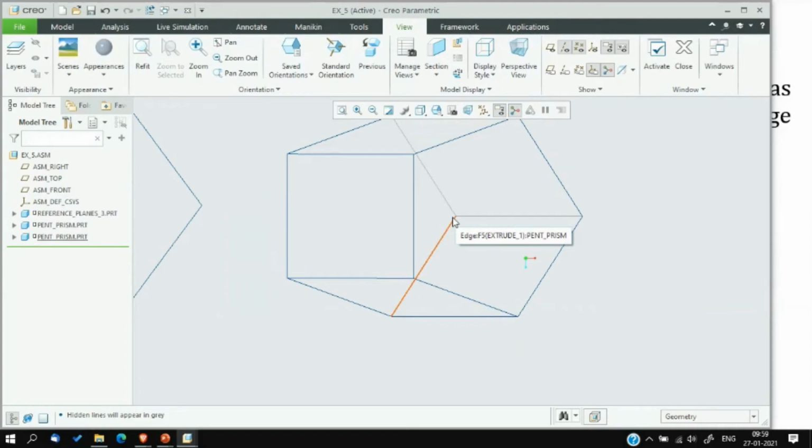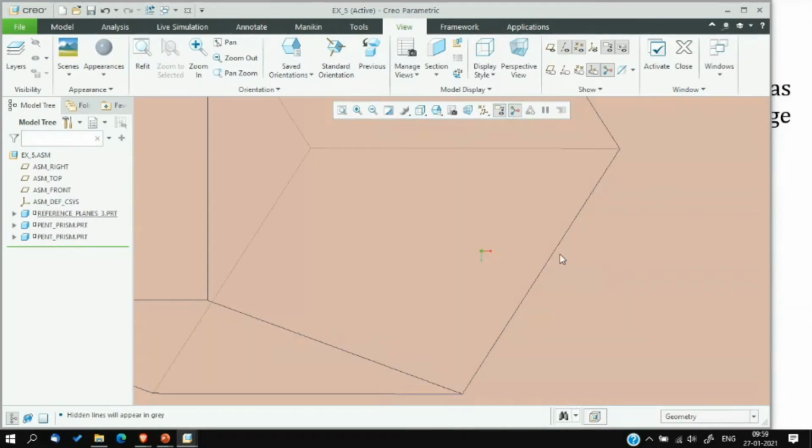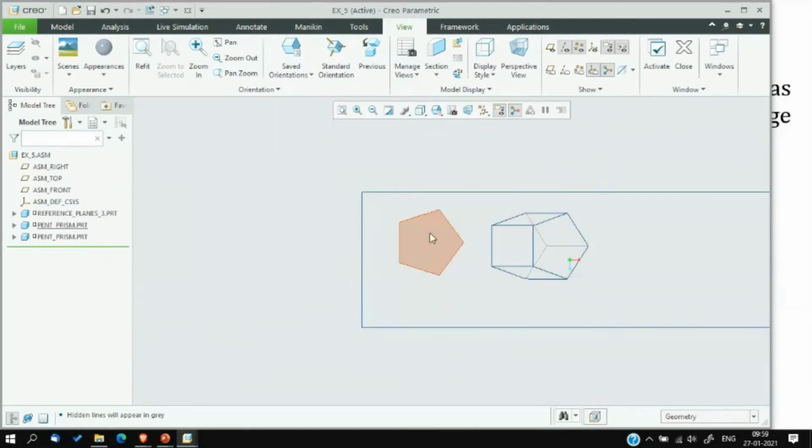So which is the top view of that bottommost corner, that also you can identify. And all the edges starting from the bottommost corner will not be visible. Now, first we start from this pentagon, then the corresponding front view we draw. The first front view is then rotated, making an angle of 60 degrees with the XY line, that is in the second view. Then that view is projected to the top.